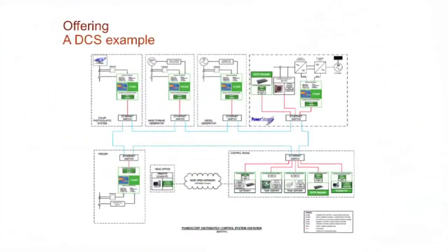That's a 64 megawatt heavy fuel power station, 6 megawatts of wind. They have a low load of 11, so 6 megawatts is starting to look a little bit above 50% penetration. Certainly if they go to 12 megawatts, they'll be going to 95% penetration at times. Very quickly, the last part of the talk is about the value chain. We have traditionally worked in all aspects of the design of these, from the consulting right the way through to the service at the end.